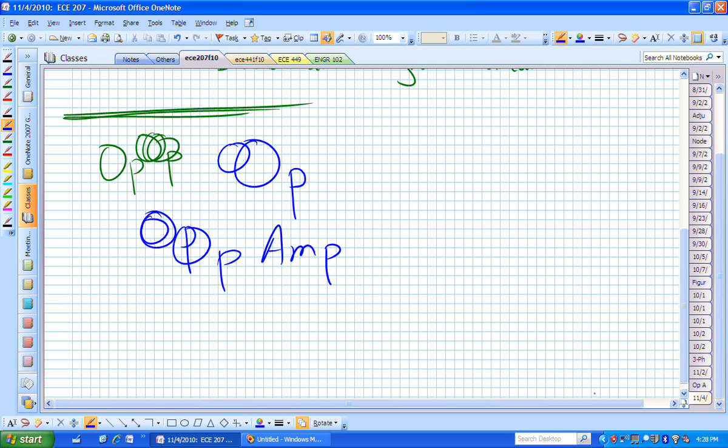What's my next drop? Minus I3 R3. Is that correct? Why is that true? Because you're going opposite to the current the way you defined that current.